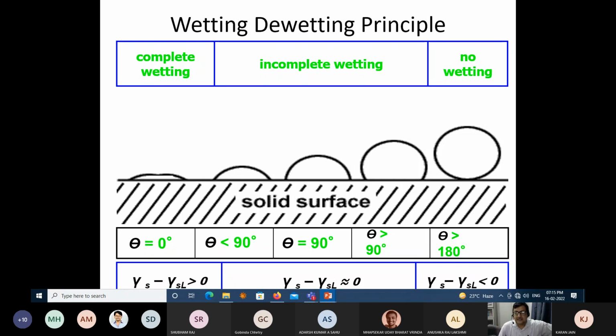how exactly, say in this situation, what is the surface? If this is a water droplet, the surface is super hydrophobic. In this situation, the surface is hydrophobic. In this situation, the surface is super hydrophilic, in case these droplets are water droplets. On the other hand, if these are oil droplets, this is an oleophilic surface, right? Whereas this is a super oleophobic surface. So different types of materials and chemicals, you can really use for hydrophilicity, hydrophobicity, oleophobicity.